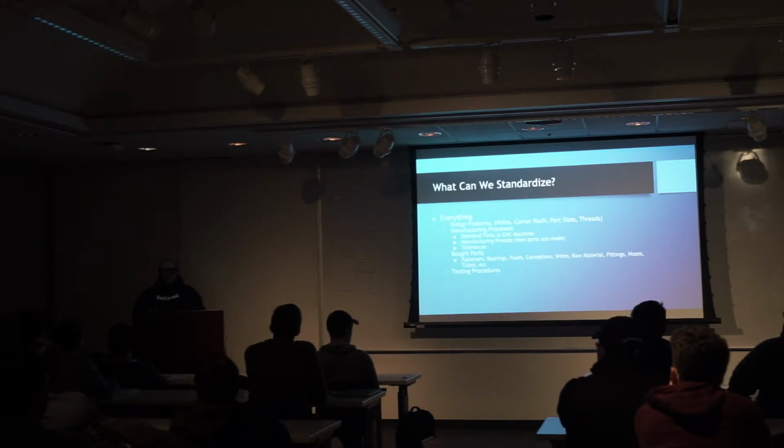But you want to try to use the same machinery, just known values, so there's not error brought in from that. You get what I mean? So if you were going to test a belt crank to see where it's going to fail, you would do a little jig with maybe a hydraulic or a pneumatic cylinder applying the force.